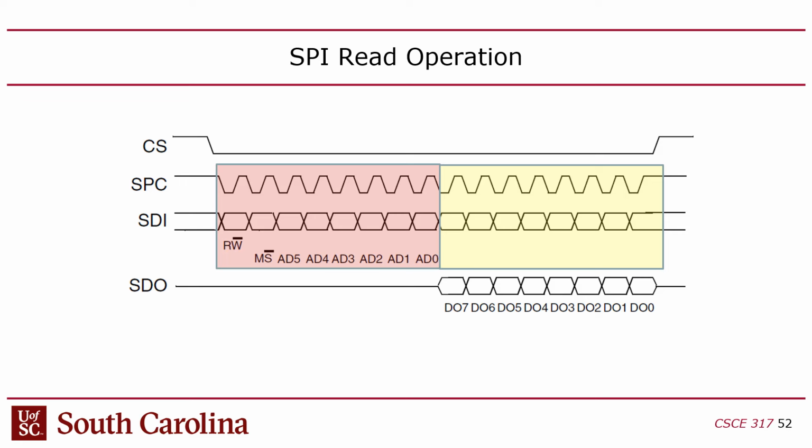Chip select. Again, here we don't say which one, because you will anyways see it from the data sheet or from the timing diagram. But in this case, we only focus on clarifying how to read and how to write. It may be different in the data sheet. It can be least significant bit or whatever, but most times you get the most significant bit first, which indicates read or write, and then you get the address. And here, if it's a read operation, the slave should output the data on the next 8 bits.